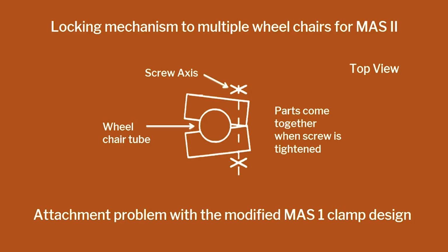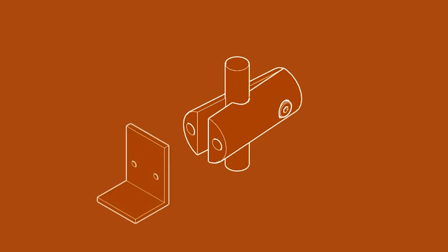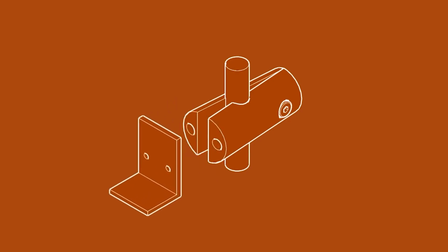This is the top view of the arm support, right? This is where the bracket is. If I tighten here, what happens? It forks. These two elements here and here, where there are two screws, they should form a plane. They are no longer a plane. So it's not going to work over a period of time. The whole thing is going to collapse. So then you can think of another solution.